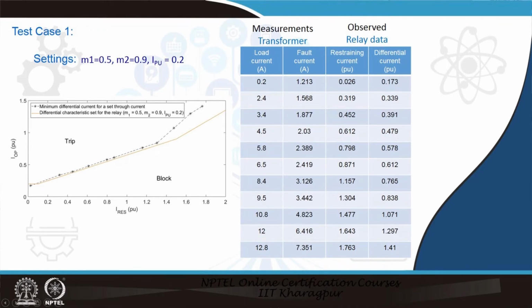What you observe in this experiment is a little bit of deviation, and this is because we are varying the minimum current to the fault current path in the resistance. So, the smoothness of the resistance decides the corresponding current. Therefore, the minimum current going on increasing leads to a little bit of error here. Otherwise, it is clearly observed that the relay performs as expected, as set for the particular case.